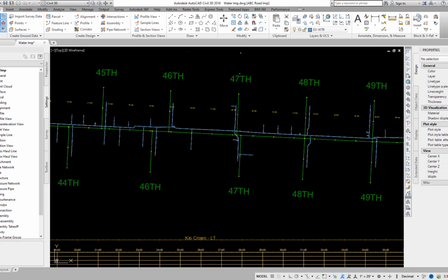Water lines are generally installed with a normal depth of cover between 2.5 to 3 feet. Where there is an obstruction or a conflict with another pipe, the water pipe is generally deflected around such obstruction or pipe. Drainage and sewer pipe are under gravity flow, and the elevation thereof cannot easily be adjusted. Unless there are other restrictions, at locations where a water main crosses a sewer main, the sewer pipe should be below the water pipe with a minimum vertical separation of 18 inches between the OD of the two pipes.